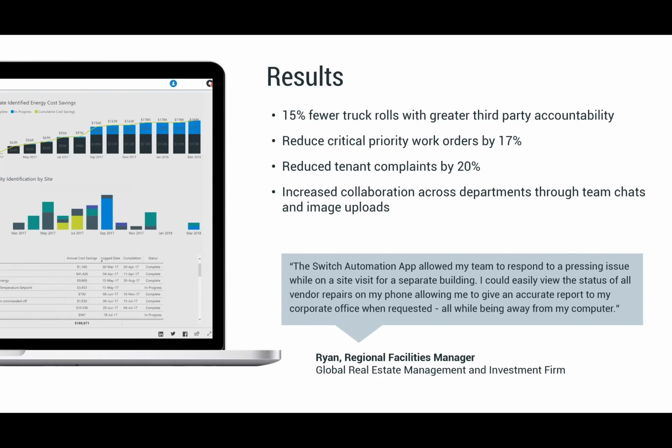The big one that we're also looking for is to reduce the actual complaints from the tenants in the building. So if you have a help desk ticketing platform where you're tracking the complaints for hot and cold spaces, we hope to see a reduction in that because we're now shifting the focus from the actual zone and the tenant complaints to the equipment serving those zones and tenants. So as your maintenance team starts to focus on those supply temperatures instead of the space temperatures, we should see tenants happy. We should see less complaints coming through on that help desk ticketing system.